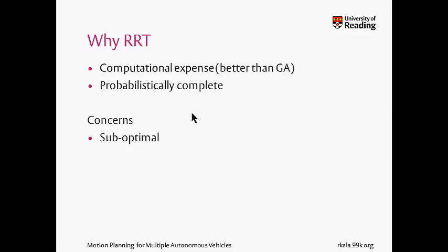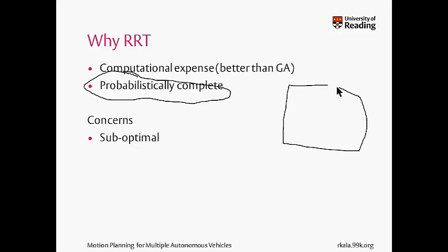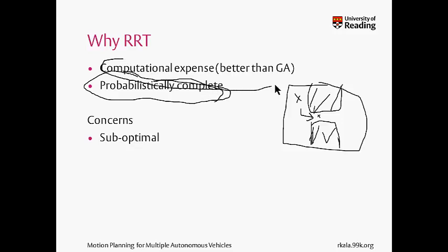As a trajectory planning algorithm, the good thing is that RRT is probabilistically complete. So if a solution exists, it will eventually be able to find it. In fact, for most situations, unless there's a very critical narrow path involved, where a good part of the trajectory goes through a narrow path like this, where all sampling based approaches really struggle to get the robot inside, because the probability of a random sample being generated inside is too low. In all other cases, RRT is probabilistically complete and it is reasonably fast.